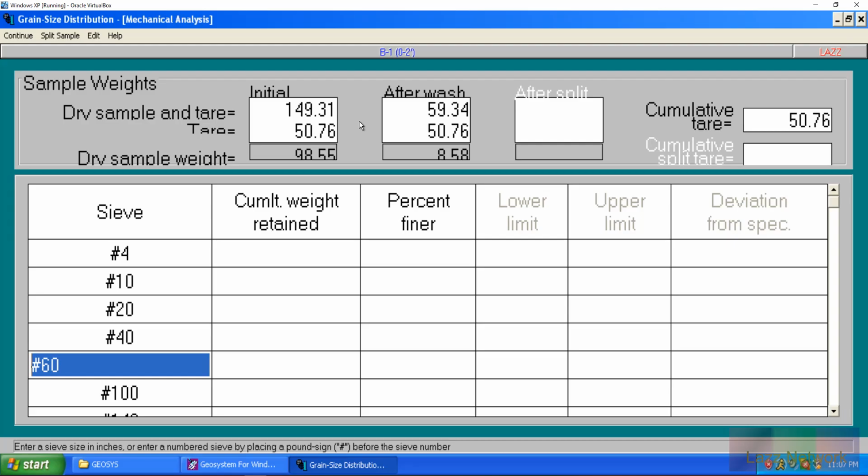And then your hydrometer. Granted there's so many different types of hydrometers out there, but you can only use 2 specific types for this test. You can either use the H151 or the H152 models. It doesn't matter what brand it is, those are the models you use, and each one gets distributed differently when you introduce it to the sample.